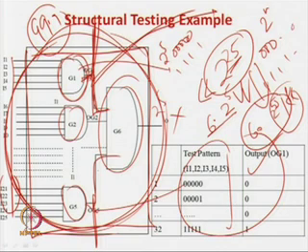So now you have decreased the test patterns from 2 to the power 25 to k, which is actually 6 into 2 to the power 5, but now you have to bring a lot of pins out from the circuit. That is actually a very difficult situation, because if you have 1000 nets which you have to observe, then you have to have around 1000 extra pins from the circuit, which is again a very infeasible situation. So we will see how to handle this. So this is a penalty of the structural test.